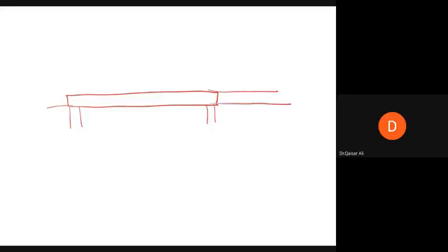Okay, so you mean that there was a beam like this, resting on supports. You say it was simply supported, but I don't think it was simply supported. It might have had continuous supports like this, maybe a support here, and the beam was continuous past this support, like this. So the bending moment diagram for this will be like this: positive bending moment and negative bending moment.